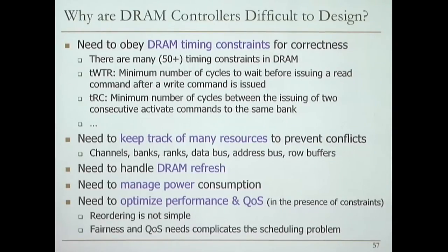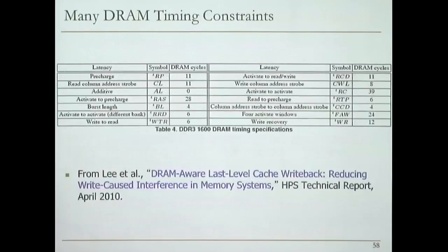For example, if you're actually displaying something on the screen over here, the GPU that's generating that perhaps needs to be prioritized at that point in time. And CPU may need to be delayed, even though that may also be doing something important, right? And they both go through the same memory controller. So there's a problem. And there may be other accelerators that are going through the same memory controller. For example, a video accelerator that's accessing the same memory, right? OK, so this actually complicates the design a lot. And we're going to cover that more. But let's take a look at some of these other ones first.